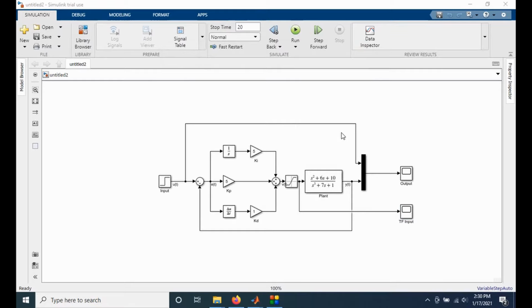You have now built and tuned a PID controller using its basic building blocks. I find that this is a very important exercise to give you an appreciation for what Kp, Ki, and Kd do inside the actual PID controller. If you lay it out like this, it also becomes very straightforward if you have to implement this on a real system. Take, for example, our DC motor.